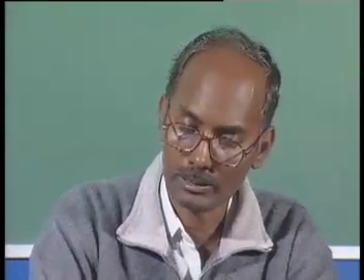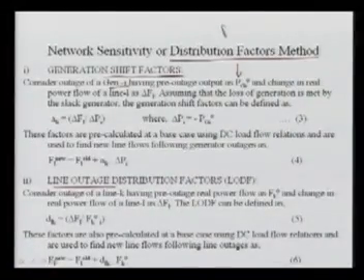Earlier the power flow in all the lines was nothing but this power flow, which I have defined here as F naught, when it was generating this. Once this generator was out, we are keeping the load constant. What will happen? The power of the outage generator will be supplied by another generator, normally let us take the slack bus power generation. So there will be rerouting of the power flow in the transmission line.